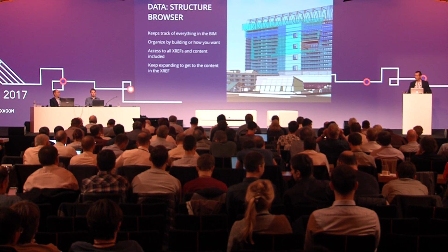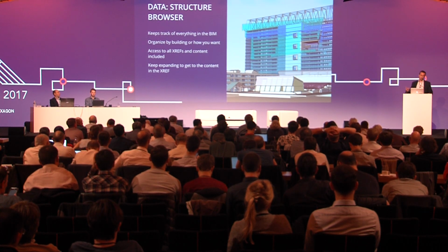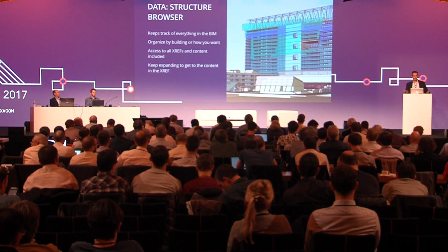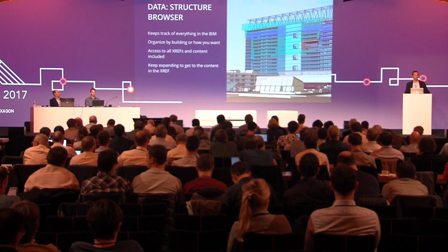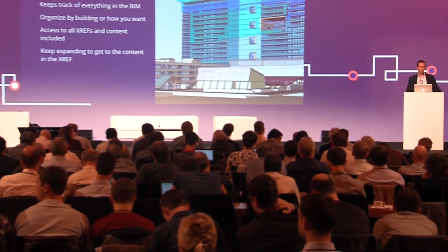And that's a bit because of the design of our BIM solution, we don't use custom entities, we don't use complex things. We use as much as possible the native entities and entity types that are available in DWG.